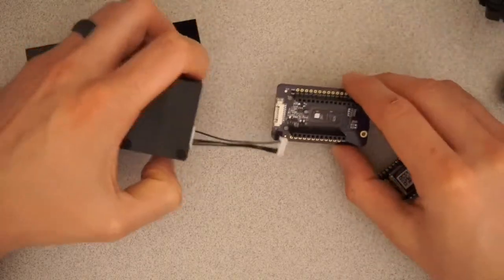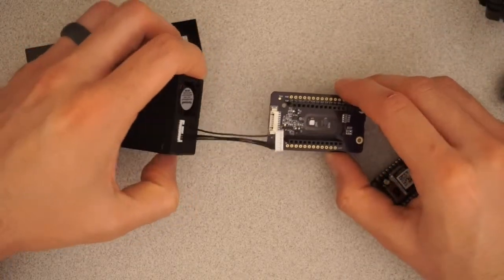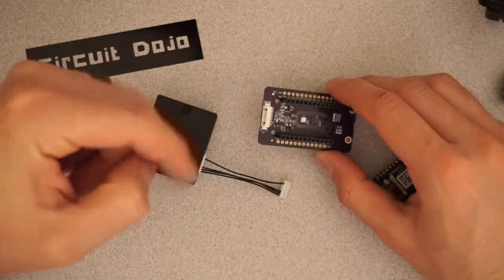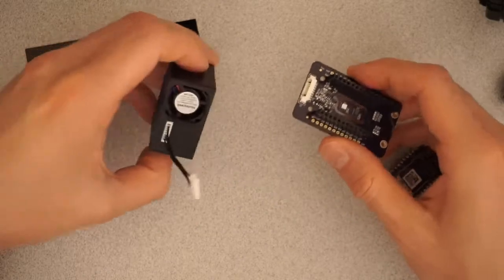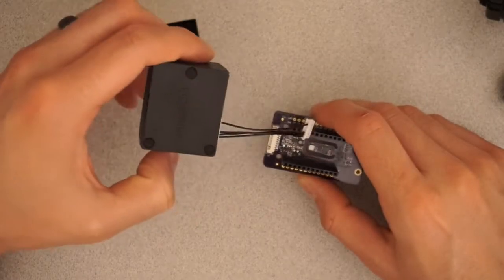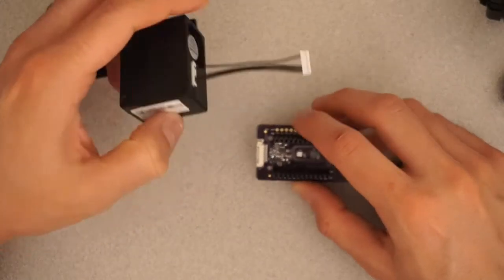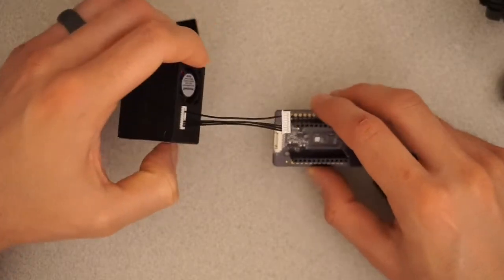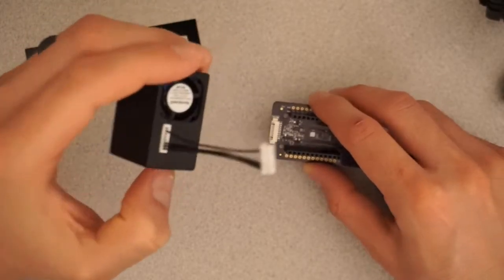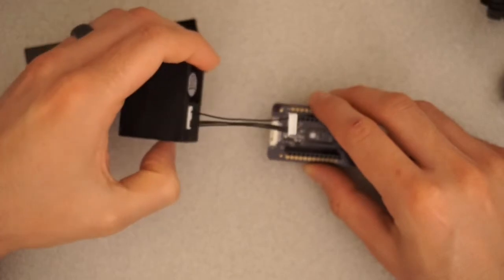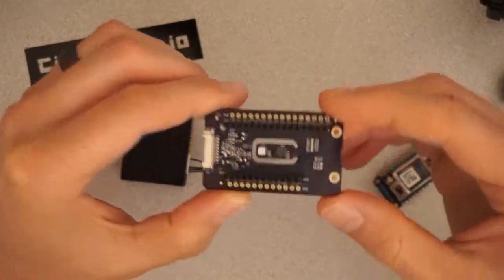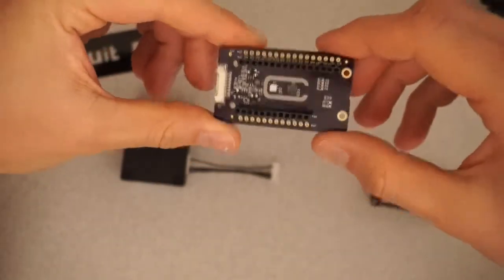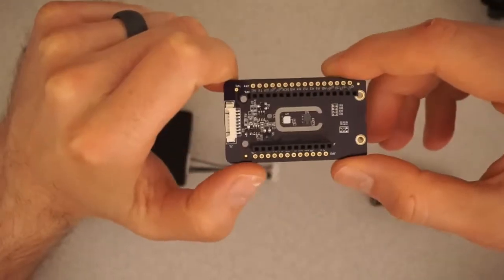In the code, if you guys check out the code, I'll have a link to that in the description down below. But the code will actually only run this for about a couple seconds just to get a new reading and then shut off. The main reason for that is that every time you run this motor, it's about 100 milliamps or so. So if you're running everything together on a battery, you'd kill that battery pretty fast.